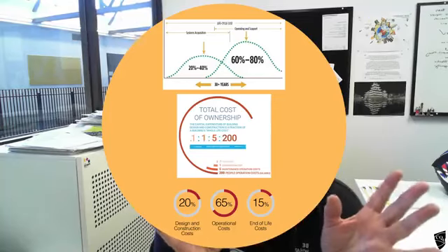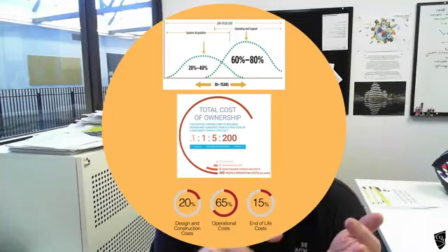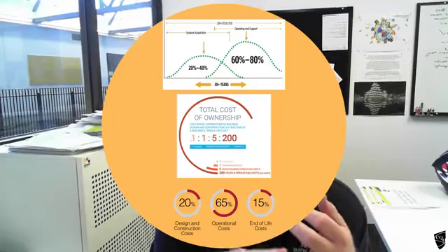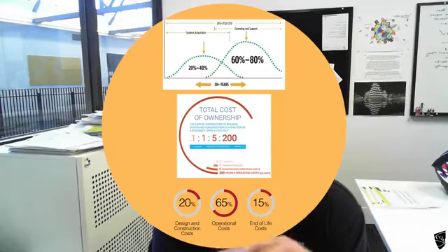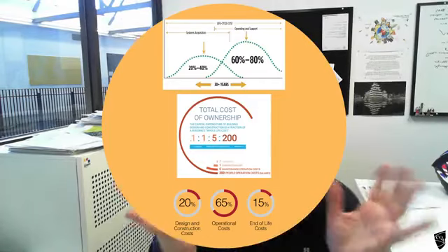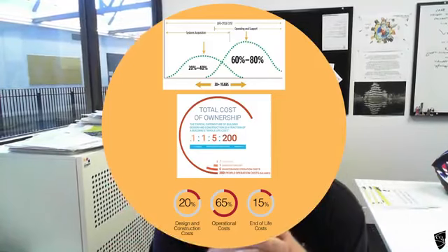And then to operate the building, which will be your regular maintenance, your breakdown maintenance, planned, reactive, utilities, minor repairs, upgrading where legislation requires it. That'll easily get you up to the 80% of the whole life cost over 30 years there.